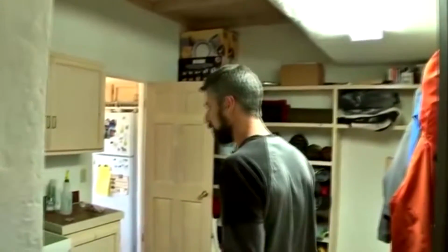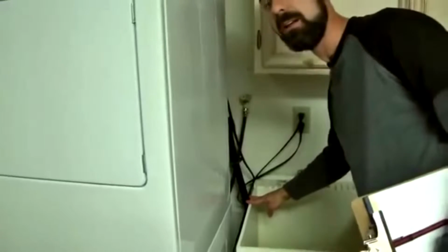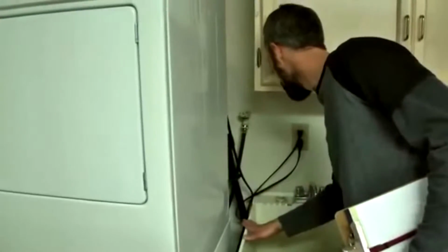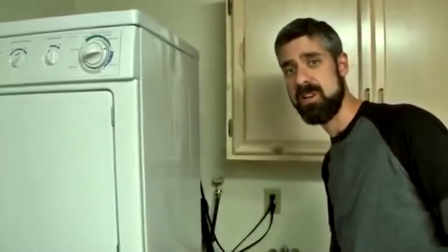Let's take a look. So as I walk in here, I'm looking for basically any penetrations in the walls. We've got some venting for the dryer. We've got a gas line coming in. We also have some water piping. So when we're looking for our air sealing measures, places that are leaking, these are some spots to check. We've got our access to the crawl space.